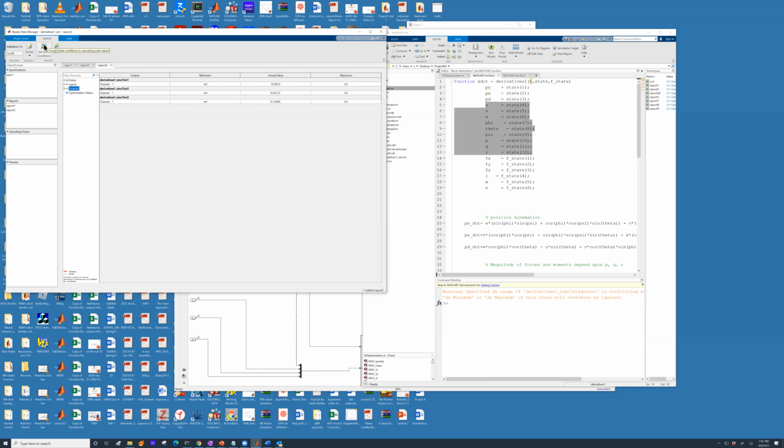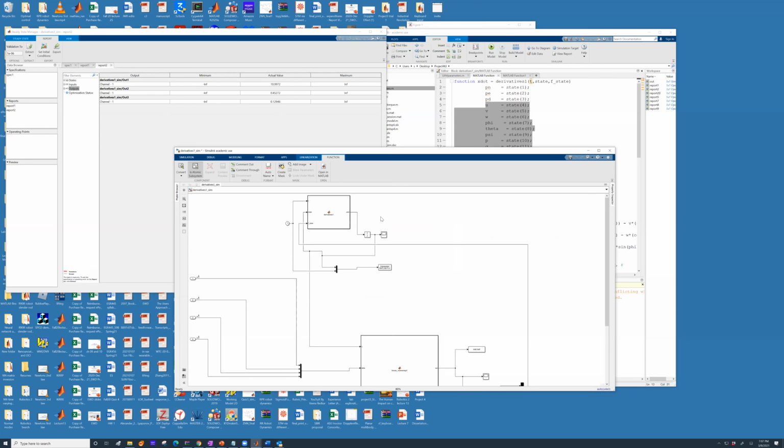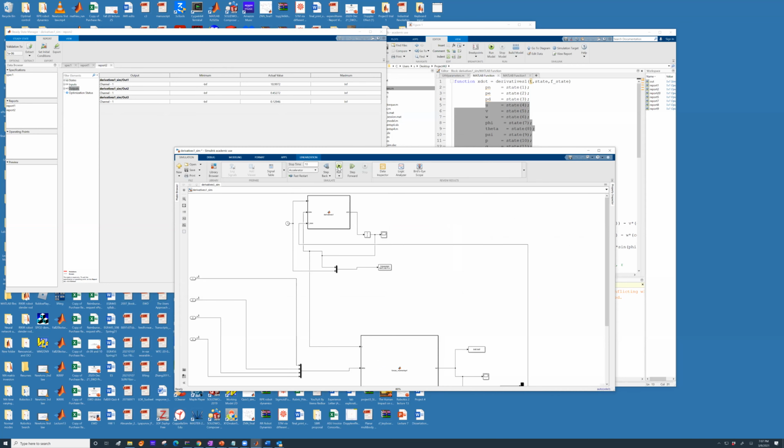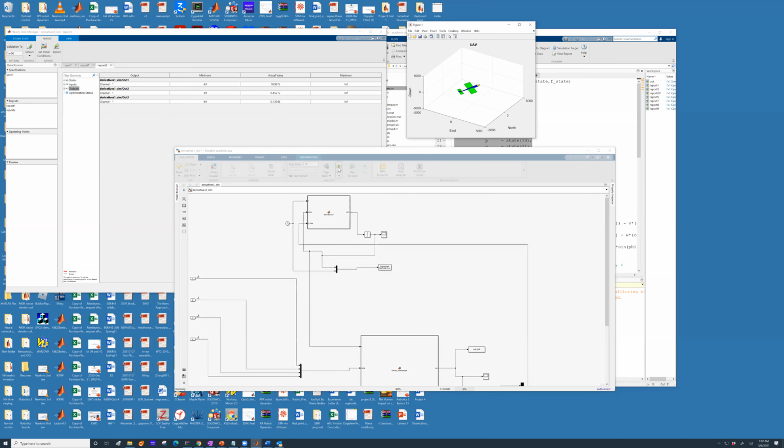And then what I will do now is I will set the initial conditions, and then I will go back. I set the initial conditions. So please note, exported report to Matlab, which is used to initialize derivative 1. And then I will run the simulation and see what happens. You will see the aircraft has yawed a little bit, because that is the trim state for Zagi.